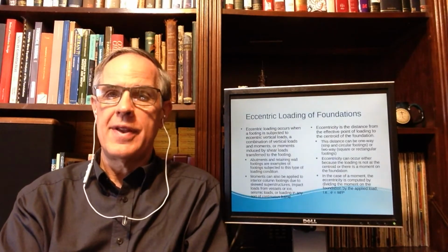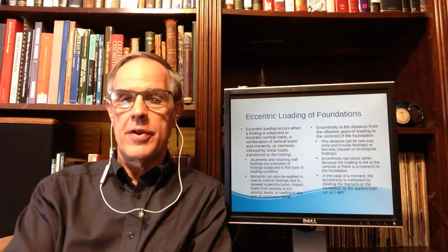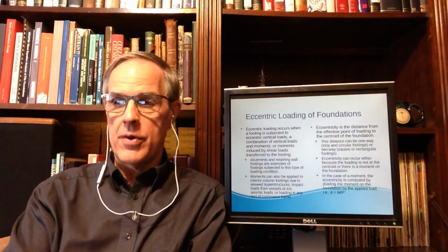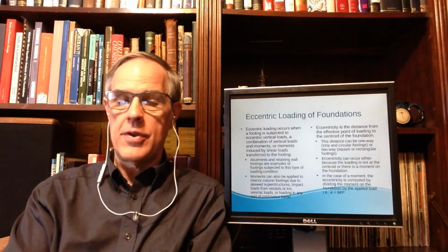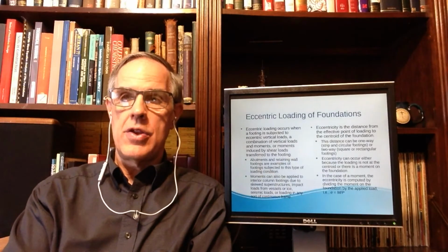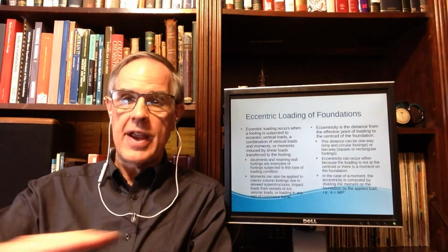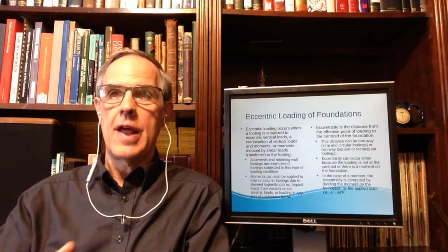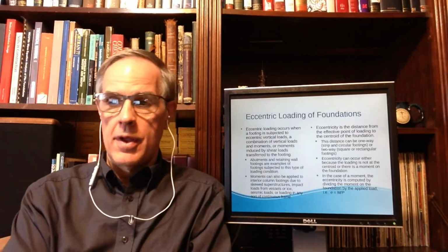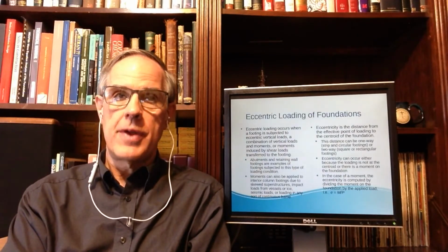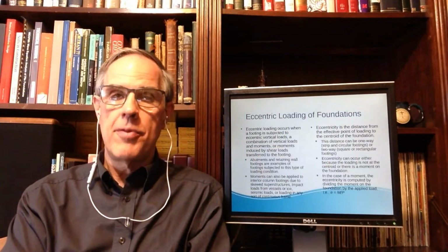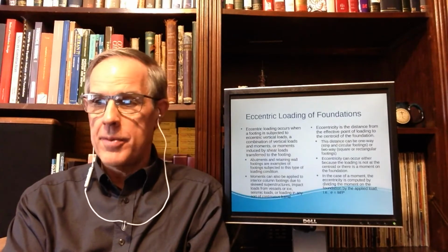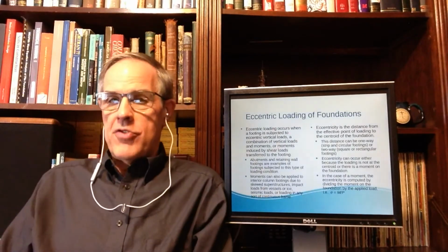Loadings are frequently ideal. In the ideal world, a spread footing would never be eccentrically loaded. However, in the real world, they are, and they are for good reasons. If you've got limited real estate and you need additional bearing capacity area under it, you can't always get that concentrically from, say, the columns if the columns are close to something else. So you can sometimes extend them backwards. And sometimes moments get added because of different types of loading and whatnot. You'll get moments. Let's make some definitions.